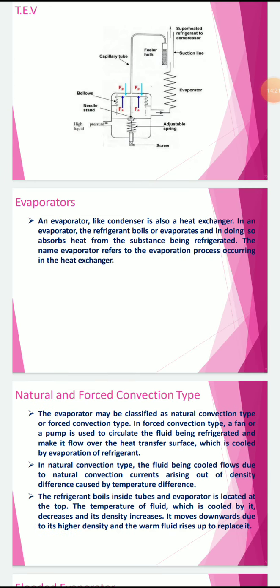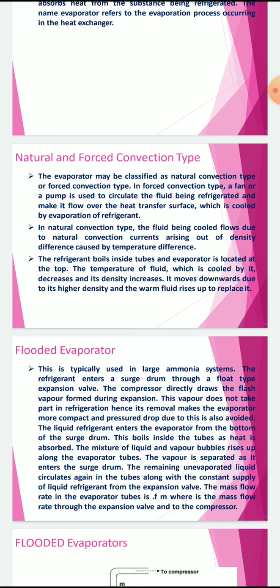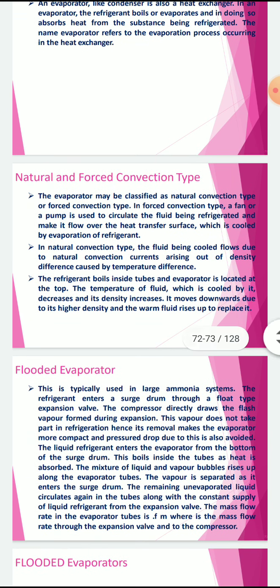Heat exchanger, natural and forced convection type. The evaporator may be classified as natural convection type or forced convection type. In forced convection type, a fan or a pump is used to circulate the fluid being refrigerated and make it flow over the heat transfer surface, which is cooled by evaporation of refrigerant.